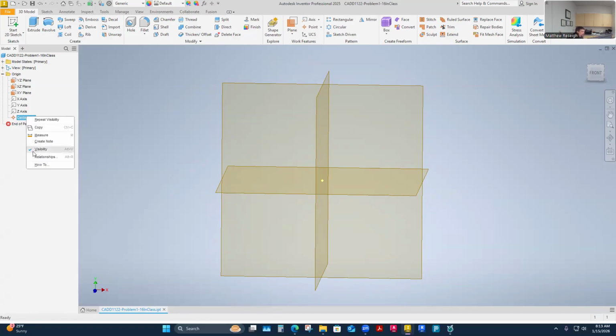I tend to not do that as much as I just project that geometry into my sketch. I usually always project my center point geometry in my sketch, whether I select it from that side and project to it, or, if you start your sketch with your line starting on the center point, it'll constrain everything to that center point. So there are a lot of different ways to lock into the origin. You could dimension to it, too. But let's do 116 though.